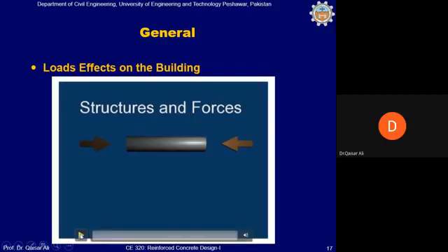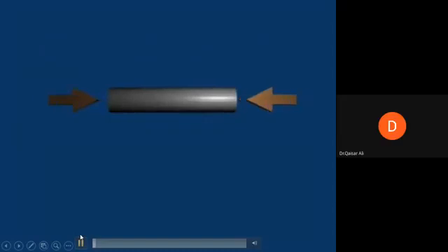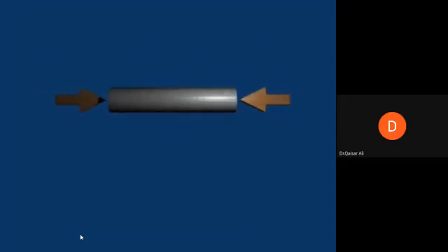Okay. In the first animation, there is a steel bar, or let's say that this is made of concrete, and it is being pushed inward. So this pushing inward will tend to shorten the length of the member. And also you can see slight bulging from the center of the member due to Poisson effect. Okay, you can also see now the tensile stresses. This is the stretching of the member, which is now causing a decrease in the diameter, or the area, of the member at the center of the member. Okay. So this is tensile, this is called pulling.